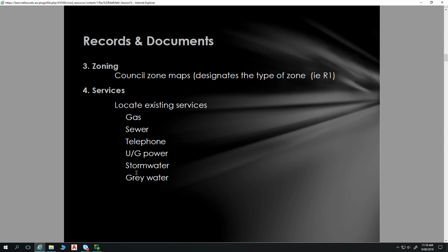checked and serviced. There's also the requirement that those on-site wastewater facilities be checked every 3 months, so quarterly. The people who produce those systems typically get the contracts for doing it. You can actually get certification to be one of these waste treatment inspectors. TAFE does it here, and I've looked into it myself, because to get somebody out costs about $150 a time. So 4 times a year, that's $600 a year for somebody to come out and say yeah, it's working, and chuck the tablets in.